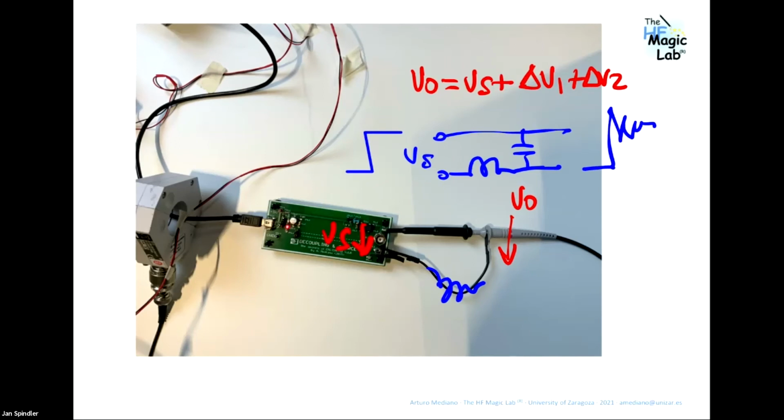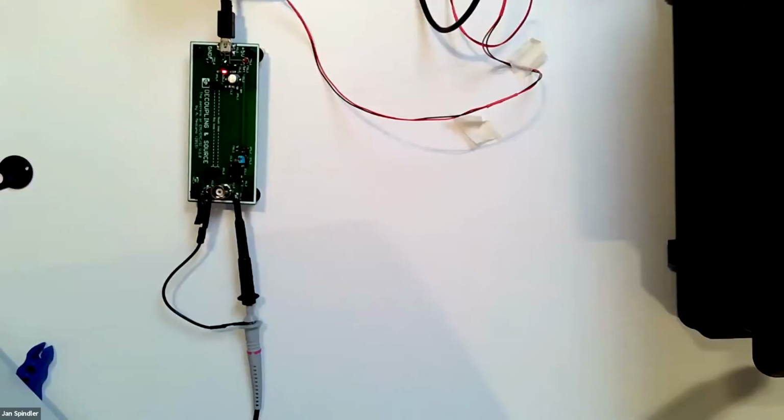And additionally, we have another problem. We have a loop. And this loop can pick up noise from areas around the PCB. So if you put your probes on top of some kind of power electronic circuit, this loop will pick up noise. This loop is related with this voltage, and this voltage comes from Faraday's law. Big loop, more possibilities to pick up. That is why I am going to switch to this situation.